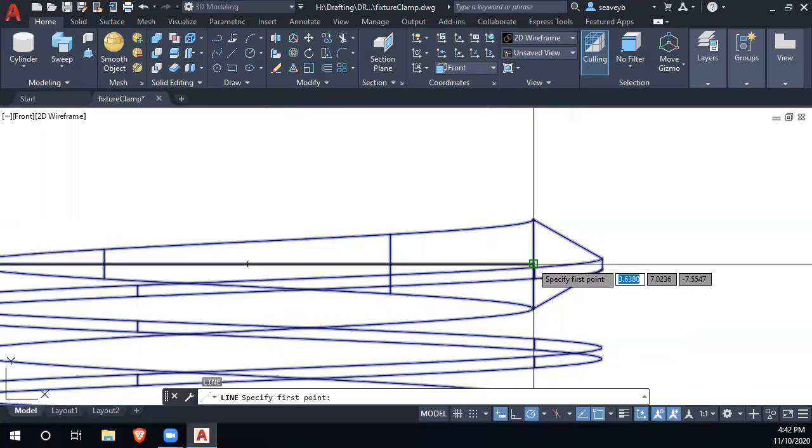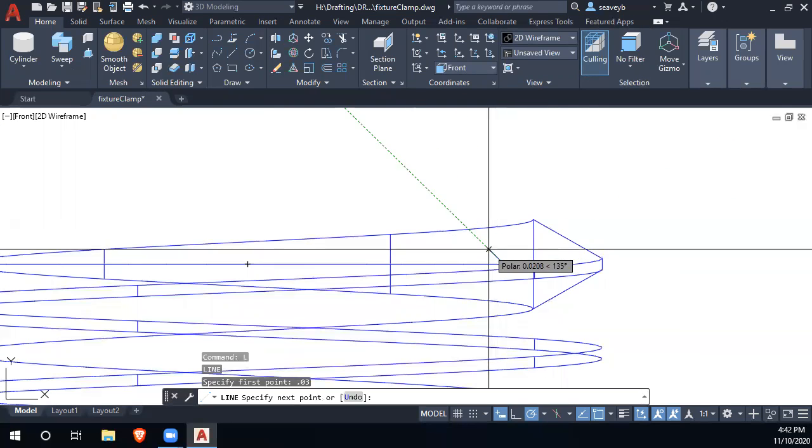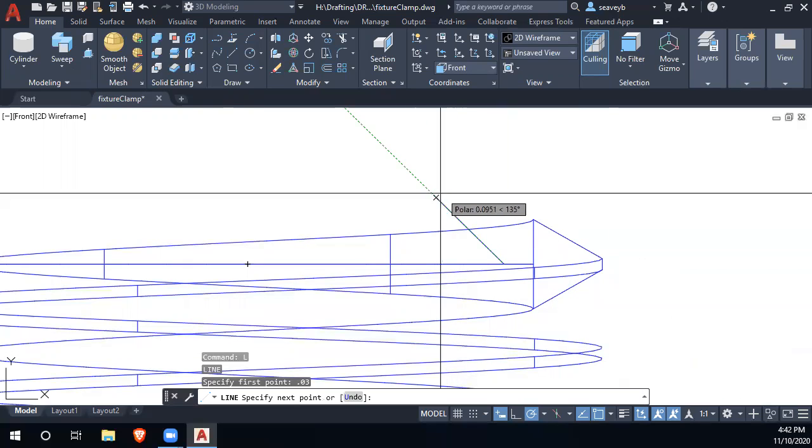I'm going to start at the end point here and come in. And I could decide how much to chamfer it. There's no real indication on how much chamfer, you could look it up. Oh, actually it does say. So it's a 300, so 0.03 inward. Okay, and so a 45-degree line off of that.